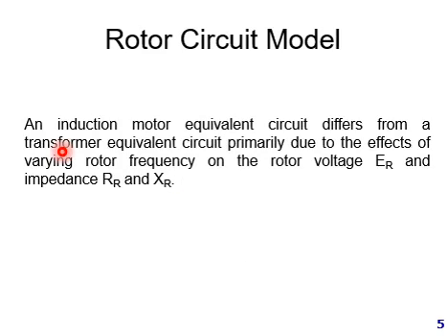An induction motor equivalent circuit differs from a transformer equivalent circuit primarily due to the effects of varying rotor frequency on the rotor voltage ER and impedance RR and XR. So these are the three parameters. Because of them, the circuit is quite different from the transformer equivalent circuit.